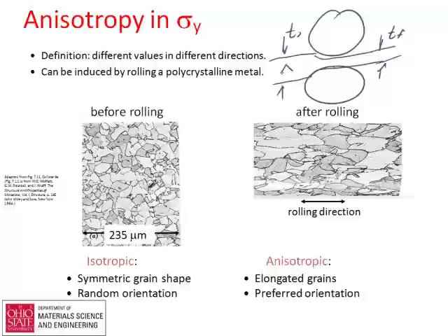So if you've got a crystal in here, imagine it starts out rather round. After it goes through this deformation, it's going to be more oblong like that. It's going to stretch in this direction and reduce in that direction. And you see that before rolling and after rolling. If there's nothing going on to reform the grains as it happens, you'll end up with grains that have different directions. You can also have preferred crystal orientations in various directions, which is, again, beyond this, but it's something you can control. It's really quite a powerful way of controlling the structure of materials.